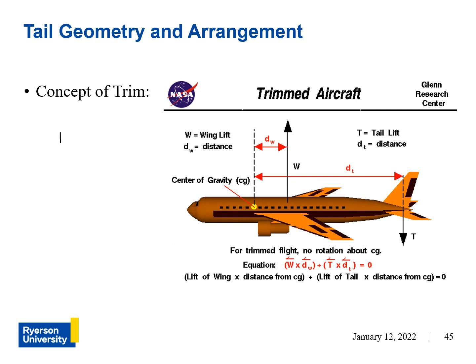So here, I guess I'll draw it. Let's say this is the lift curve of the tail. You don't want the tail's angle of attack or angle of incidence to be here, because a change in that would cause it to stall, and then you lose the effect of your tail counter moment to the wing fuselage body. So typically your incidence angle should be around here, so you have some allowance, so your tail doesn't stall. That's what I mean by tails being designed to operate at only a fraction of their lift potential.